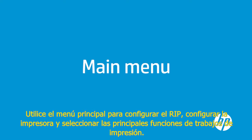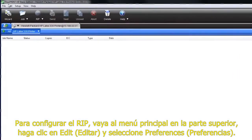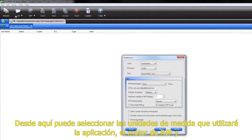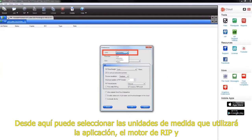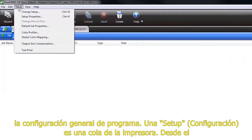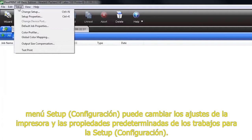Use the main menu to configure the RIP. Set up your printer and select main print job functions. To configure the RIP, go to the main menu at the top, click on Edit and select Preferences. From here you can select the units of measurements used by the application, the RIP engine and general program settings. Setup is a printer queue. From the Setup menu you can change the printer settings and default job properties for the setup.